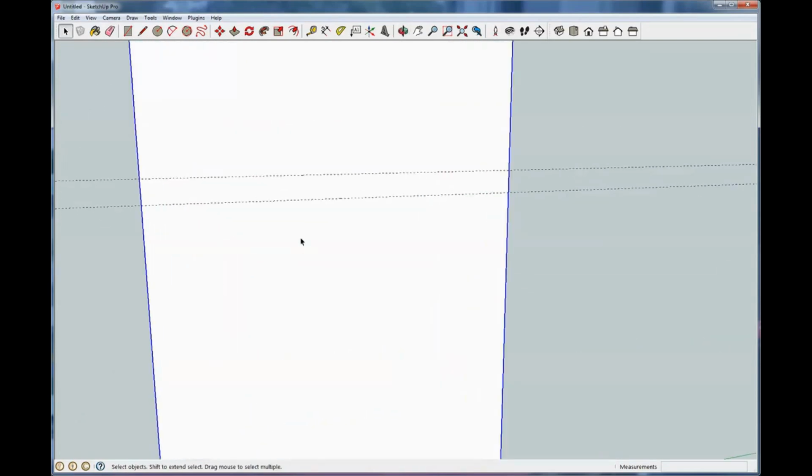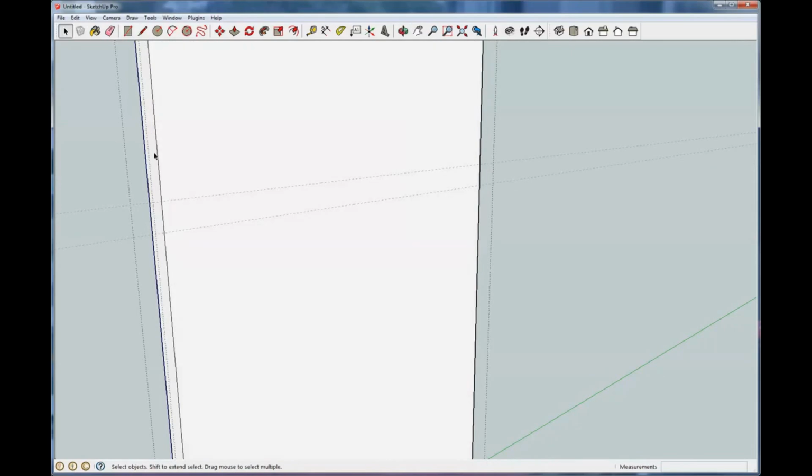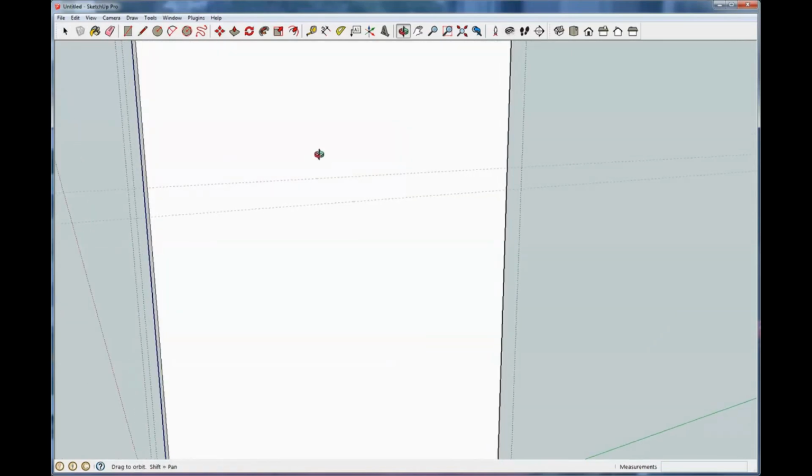But the nice thing is, I'll show you how this works. Let's move in here, and I'm going to double click this. So we got dotted lines around it. You can see we're in the edit mode of this group, and I'm going to click the line tool, and I'm going to go out to this corner. It gives you a little indication, intersection, outside, active, and I'm going to go back here and click, and then I'm going to click the line tool again.